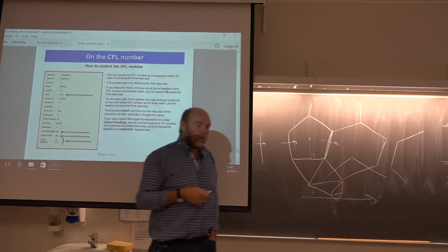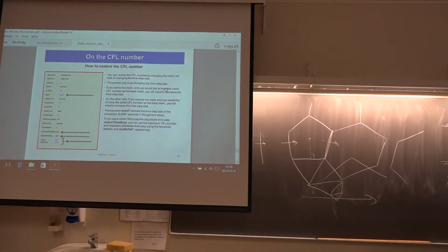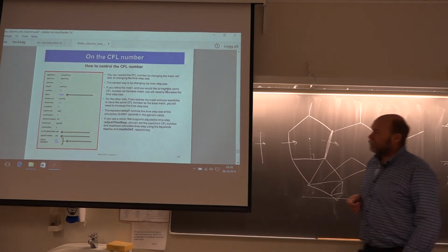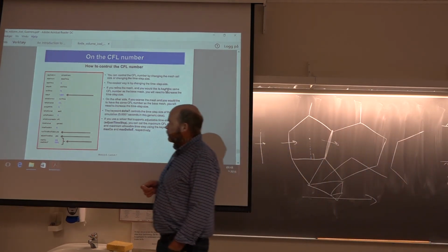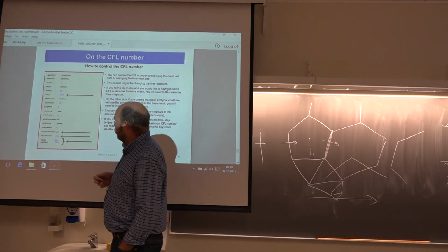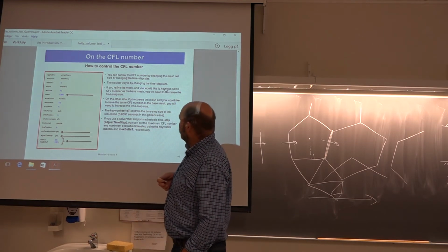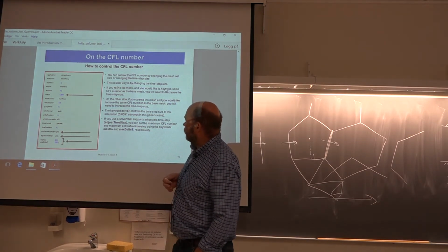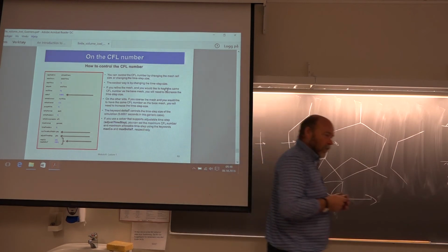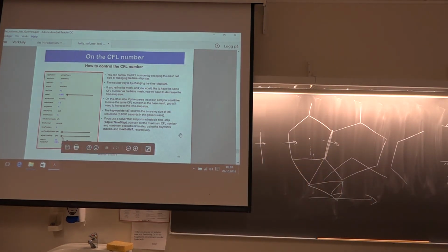What should this number be? Well, that number, the deltaT, should be so small that you get a Courant number of 1 in the end. So a little trial and error. You actually have some options down here to have an automatically adjusted deltaT so that the CFL will be under 1 automatically, or under control at least. That's actually an option.